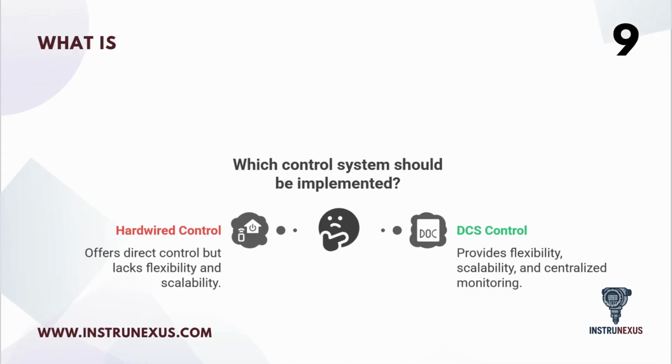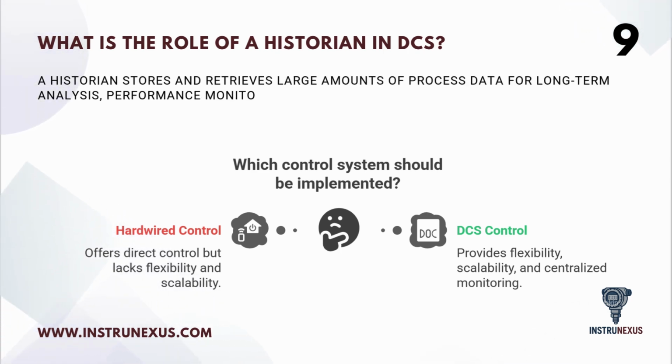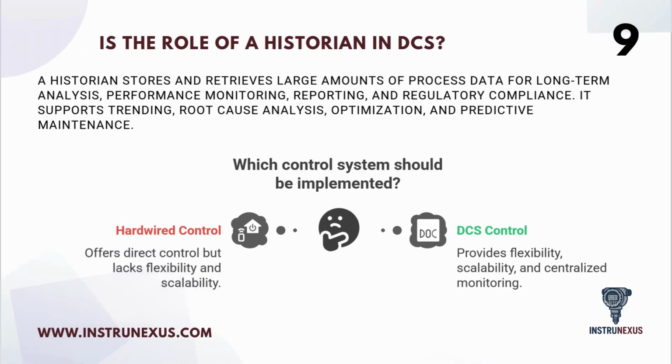What is the role of a historian in DCS? A historian stores and retrieves large amounts of process data for long-term analysis, performance monitoring, reporting, and regulatory compliance. It supports trending, root cause analysis, optimization, and predictive maintenance.